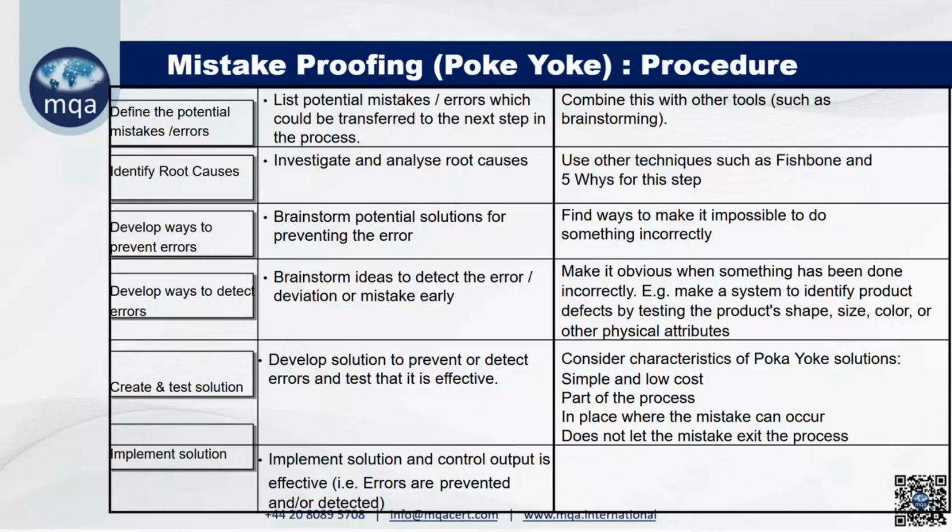Whenever you do any corrective action report, at the bottom there will be horizontal deployment. There you have to mention that these actions are taken for this product also. So one action applicable for 10 products, do it for 10 products and eliminate that defect in the other 10 products also. That is basically horizontal deployment.